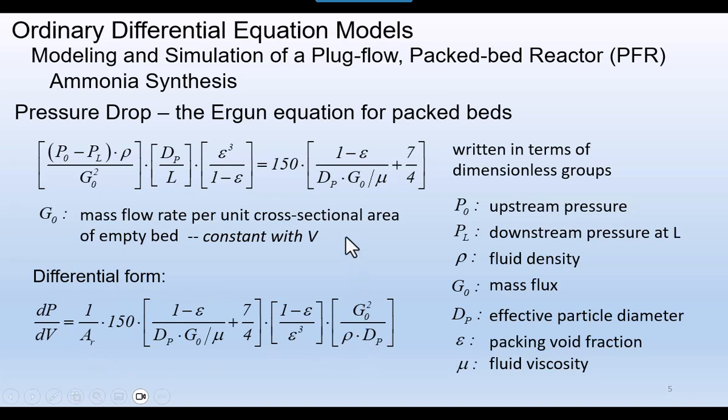So one challenge that we have to deal with here is coming up with the fluid viscosity, and we will address that a little bit later. So this would give us the opportunity to model the pressure drop, because if we are flowing gas at a high rate through a packed bed with relatively fine particles, we may have a significant pressure drop as we go through the bed.